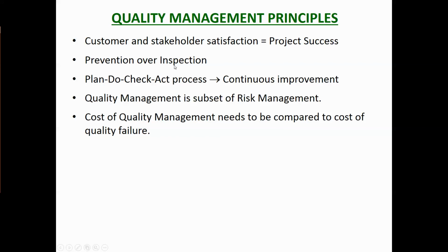Now this one here is very important: prevention over inspection. It is cheaper to prevent a quality non-compliance happening than it is to find it by inspection. For example, concrete arrives on site. If you test it before it is laid and you find that it's defective, then you can send it back to the factory. However, preventing it, what you can do is make sure that the concrete that arrives on site is going to be okay. So you would hire a certified concrete supplier that you are confident will be able to supply the right concrete. You will test it, okay, but it's unlikely that the concrete that arrives on site is wrong.